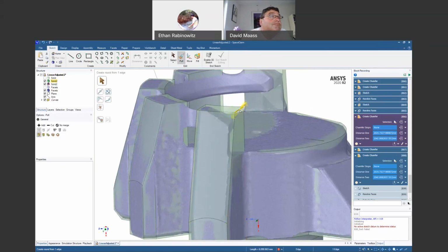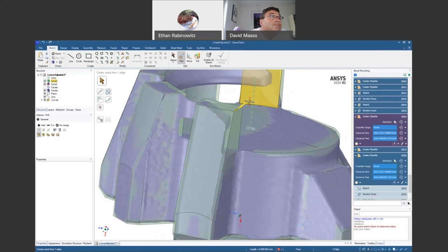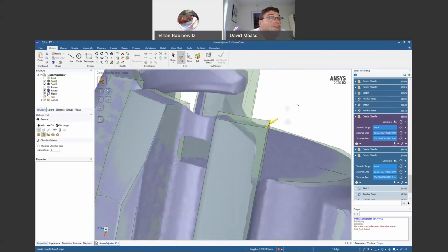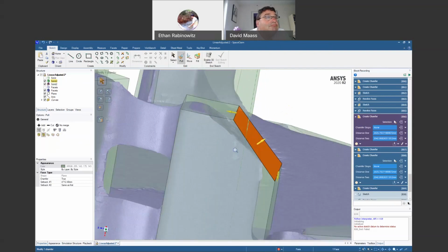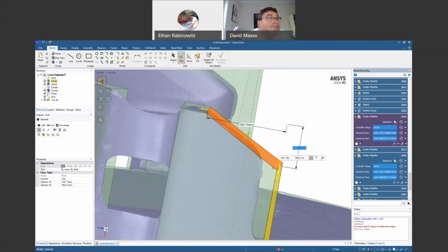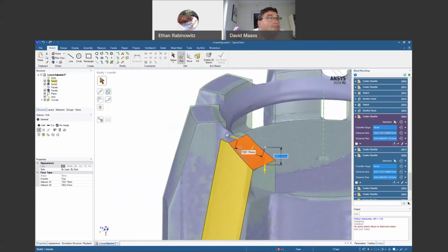Here, this is a chamfer that I think is at a non-standard angle. So one thing about chamfers, when you pull them, they do initially chamfer to 45, but after you let go of it, you could grab an arrow in a single direction and modify that. So here, if we're not quite sure what the chamfer angle is, we could go ahead and adjust it like that. And this would be as opposed to sketching a line and revolving or making a cut like that.